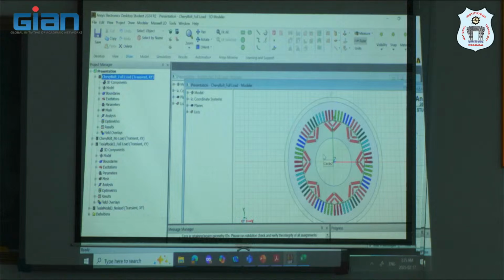One of the analyses we are trying to do is taking these motors, introducing eccentricity in these motors and seeing how they behave. So we are not creating the design, we are not designing the motors, right? We are using the correct design. We are just introducing a fault of our choice and seeing what the impact on performance is. Interestingly, we found some motors have a torque reduction due to eccentricity. So performance might not always worsen. Cogging torque worsens, but sometimes torque improves. We have to do more research. All I'm saying is these kinds of designs are also possible.